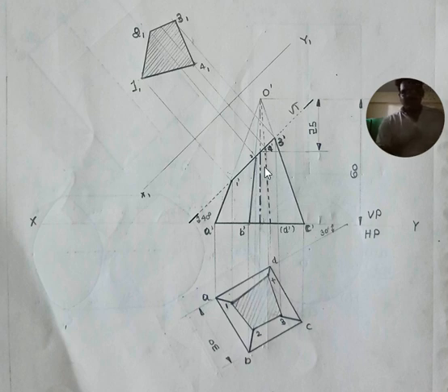The next is the section at top view. For section at top, after sectioning, you are seeing from the top of the object. When you see from the top, the bottom base is visible. Along with that, the sectioned portion is also visible in the top view. So that also we have to represent in the top view. How to represent that? We have got new corners on the slanting edges 1, 2, 3, 4. From there, we have to draw vertical projection lines until meeting the corresponding slanting edges in the top view.